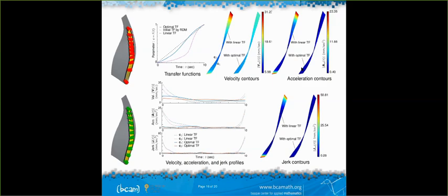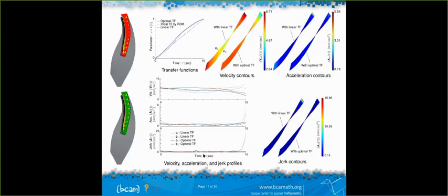In the top right, we have the acceleration color codings. Again, you see it's better or smoothed after reparameterization. And on the bottom right, we have the jerk. The jerk values are higher at both ends, and it's very smooth throughout the motion. And here in the bottom left, we see the graphs of the norm of velocity, acceleration, and jerk. And you can see they are very well smoothed with our reparameterization method.